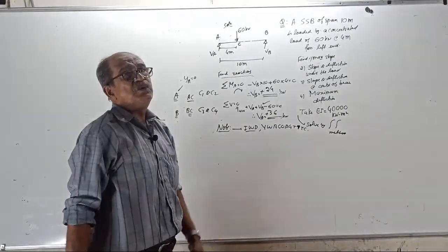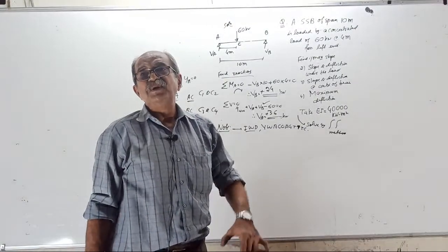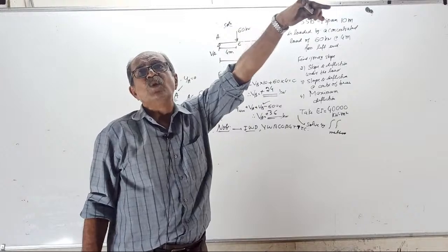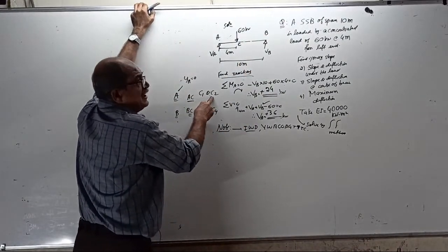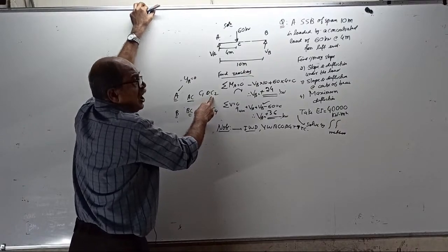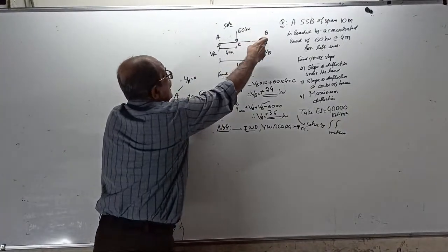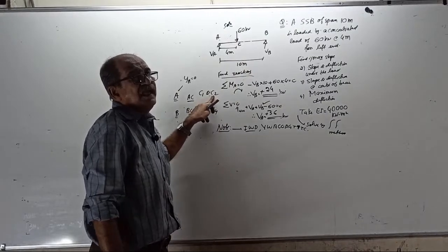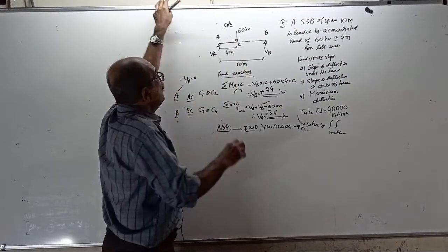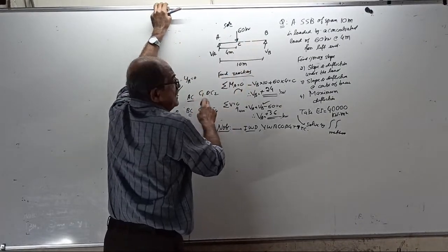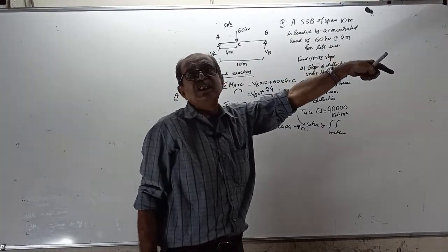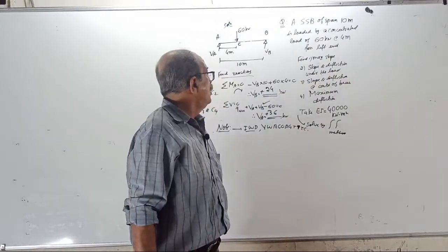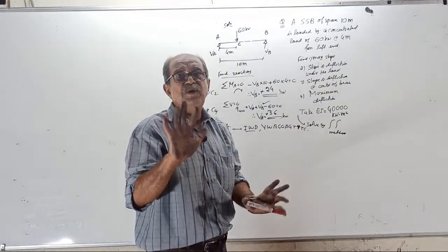We wanted one extra equation, which resulted in two more unknowns. See, here C1 is there, and you have one more unknown, C2. To solve for C2, you want to use YB equal to 0. Some will say, yes, two conditions. But when you take a section there, these two over, two more unknowns will come, some other C1, C2, which I can call C3, C4. Then how to solve, I will tell.